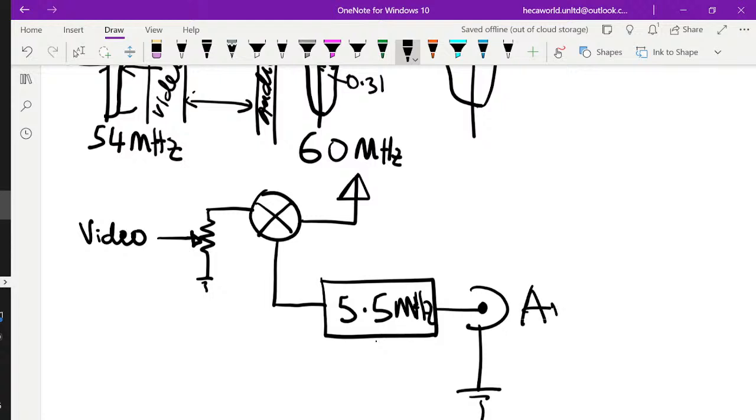and then this oscillator is modulated by an audio signal. So audio in, and this will be video in. So you can vary the signal here. In some cases, you might want to have a capacitor here. Again, we always use capacitors at the input to isolate the DC conditions. So you can do the same here. Isolate DC conditions of the sources.